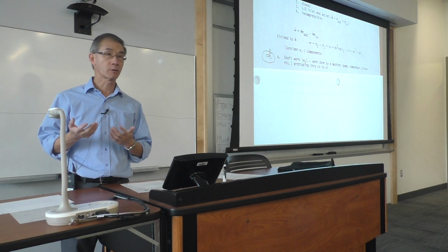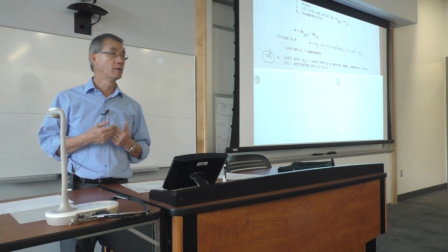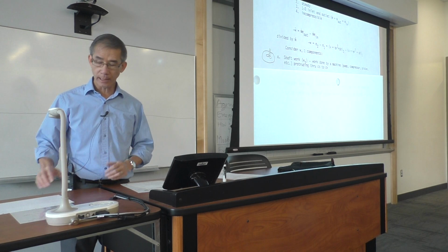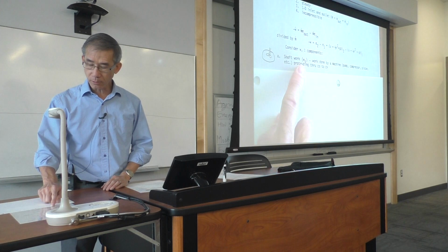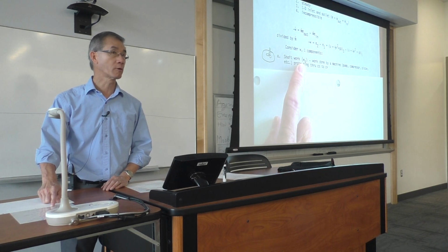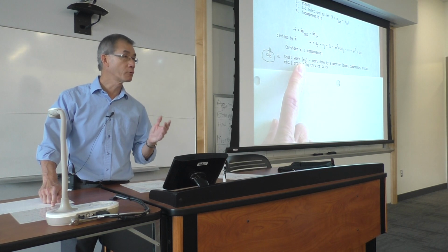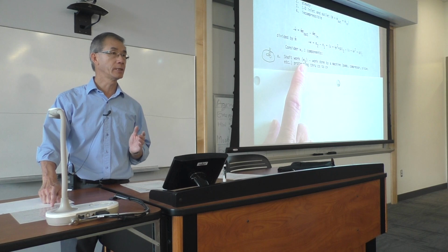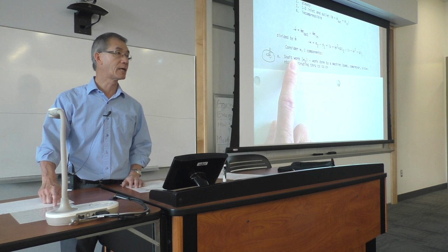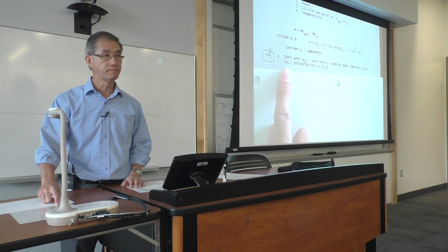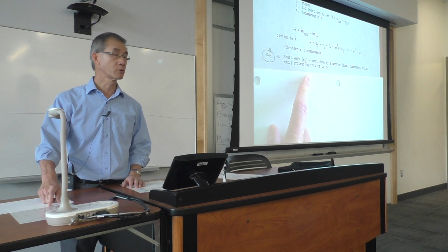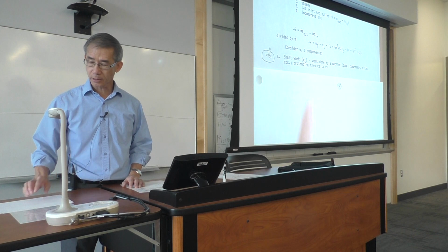Or if it's a hydraulic turbine, I'm taking energy out of the water as it goes through my turbine. That's what I now call the shaft work: work transferred in and out of the fluid due to machinery penetrating into my device or control volume. Those are the typical control volumes of a pump, turbine, compressor, etc.